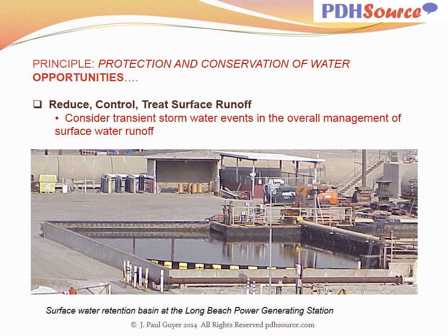municipal wastewater system. That can create problems downstream for whoever's managing the municipal wastewater undertaking in this community. But here the rainwater on this site is channeled to collect into a retention pond, and then it is released slowly over time, so it reduces the surges in the quantity of stormwater runoff.